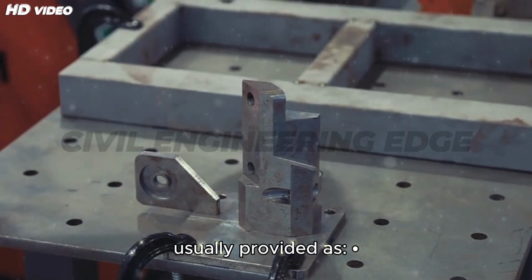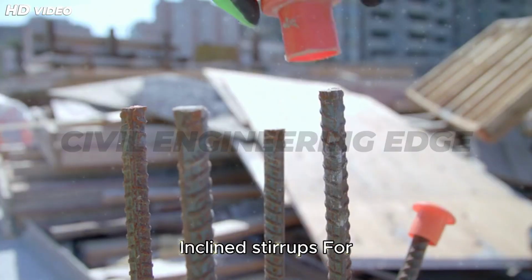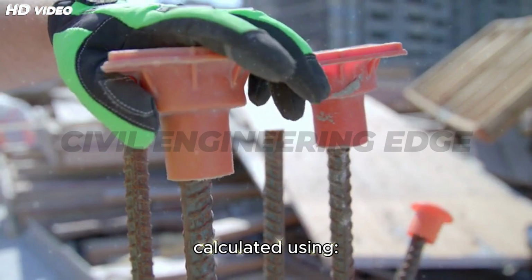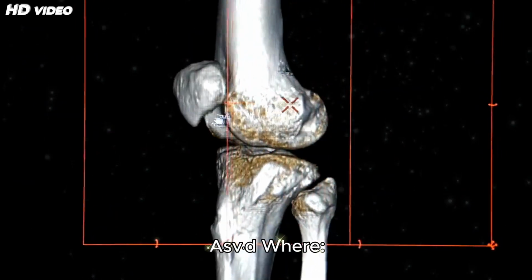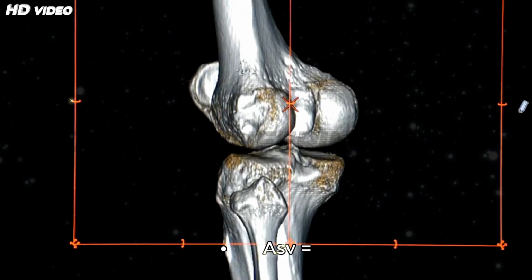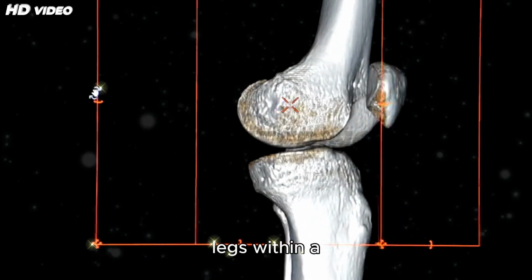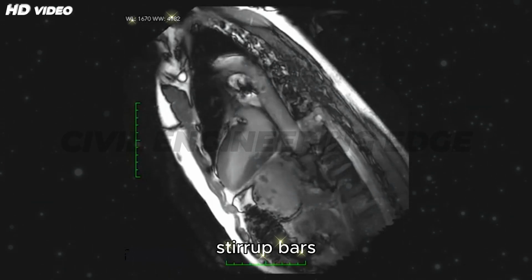Shear reinforcement is usually provided as vertical stirrups, bent-up bars, or inclined stirrups. For vertical stirrups, the spacing s is calculated using s equals 0.87 fy Asv d divided by Vus, where Asv equals the cross-sectional area of stirrup legs within a spacing, and fy equals the yield strength of stirrup bars.